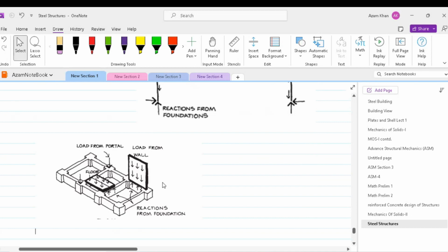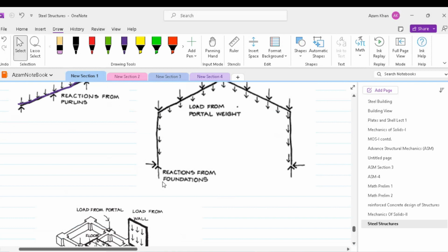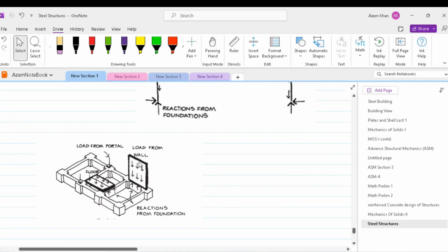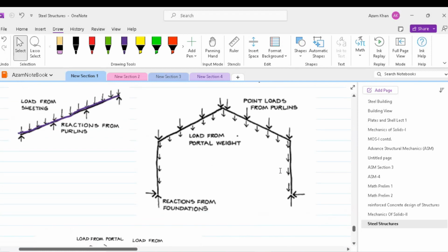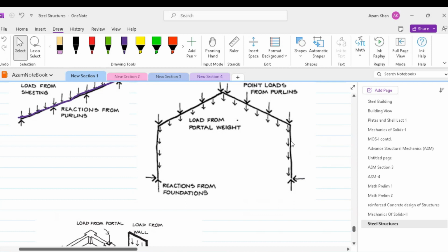We can realize that the load of the walls and the floor units are directly transferred to the foundations, although apparently the masonry wall might seem connected to the portal frames. But the connections are just to ensure stability. They are not meant for transferring the loads to the frame.